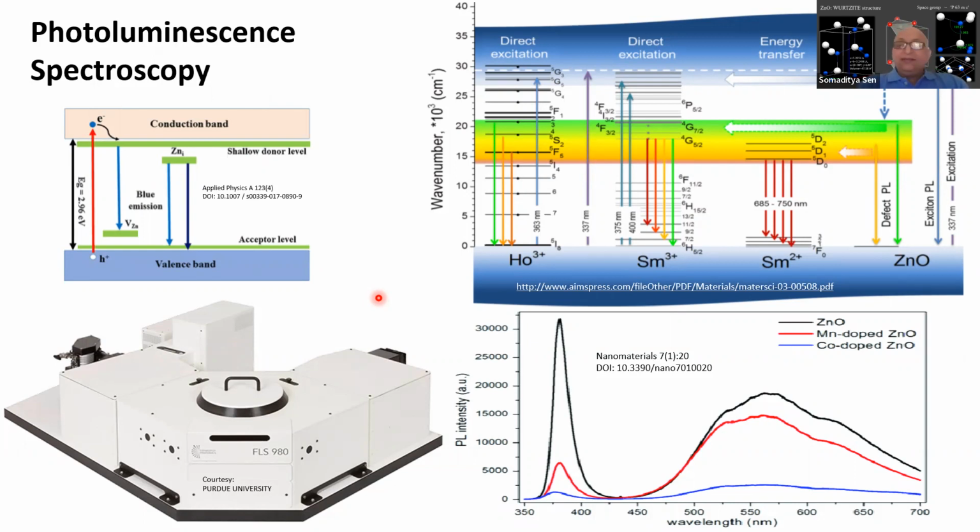Now, but the lattice cannot remain without oxygen all by itself because otherwise the lattice will be charged. That is not possible. So what it does, it compensates that loss either by putting another oxygen interstitial into the lattice, which can counteract the oxygen defect, or it can create a zinc loss, so a zinc vacancy. So we can create zinc vacancies and oxygen vacancies simultaneously, or oxygen interstitials and oxygen vacancies simultaneously. So these types of things can happen.